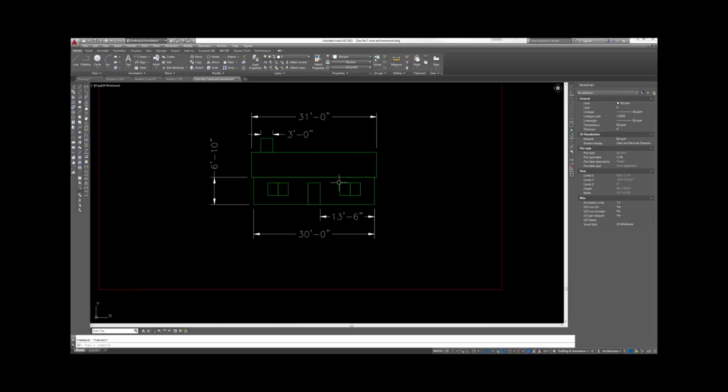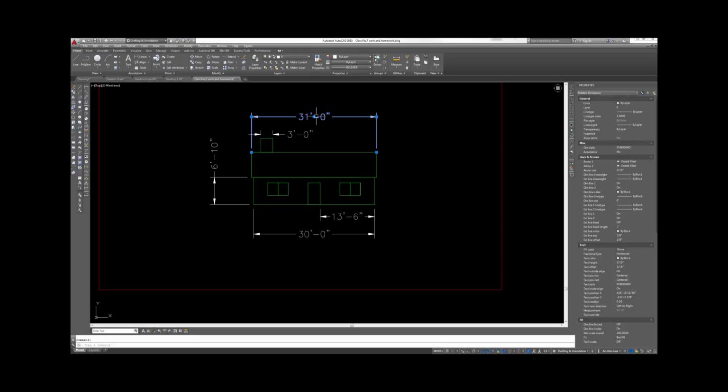Over here, some of the dimensioning we worked on, if I select this dimension that's already been created and I hover over this grip here, it allows me to do a number of things. One, I can move it above the dimension line, so just select that. I can come back, hover over it, and reset the text position. I can move text only, so I just want to move the text out of there, and it gives me no leader.